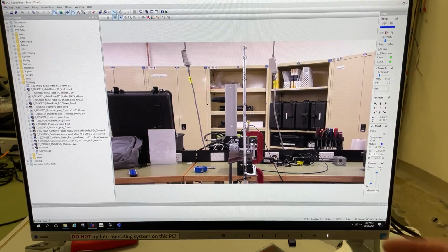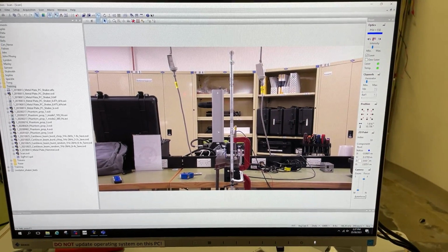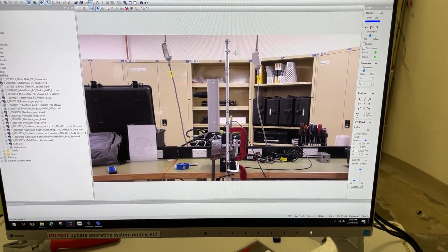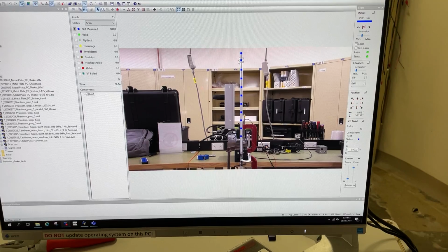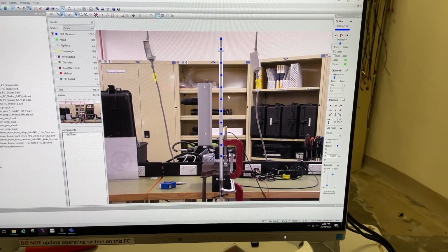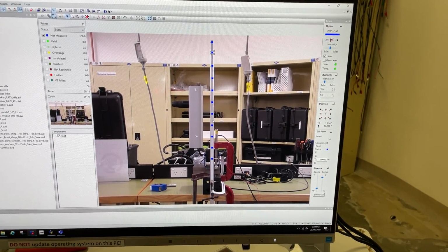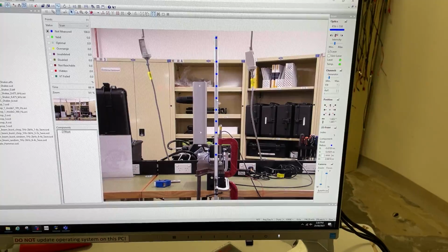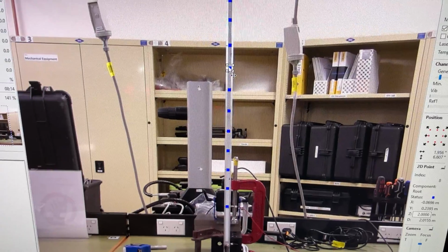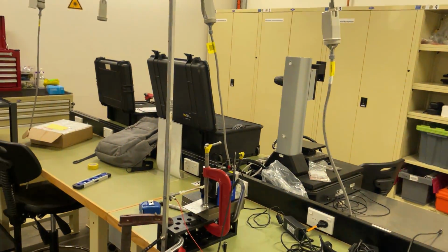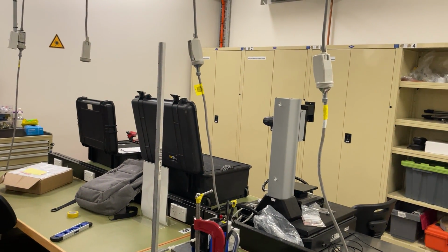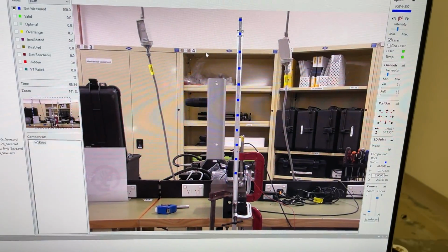We can also do 3-dimensional alignment, which will take into account some depth, but our structure in this case is simply a 2-dimensional structure. The 2D alignment has been completed, and so we have alignment of the camera system and the vibrometer scanning system. So we can then define these measurement points, and you can just about see in the video I showed in the previous video that the laser beam moves on the structure as we click from point to point. I'm just clicking different points in here.